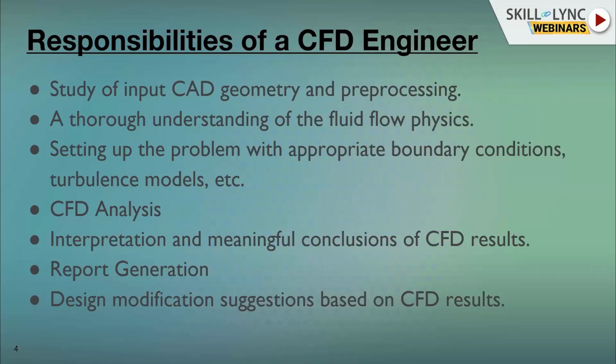When I say the study of input CAD geometry, he should be aware of what problem he is going to solve. Then he should know the real application of that particular problem. Then he has to modify or clean up the CAD geometry to meet the requirements of CFD solutions, and that includes CAD cleanup. Then he needs to do the meshing, then solver setup, etc.